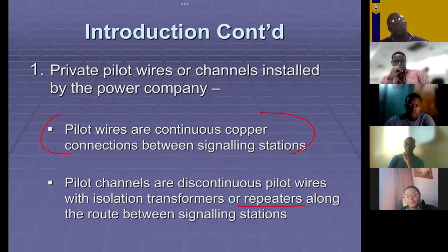Now, if you were to transmit or pass that information over the single copper wire, because you're dealing with ones and zeros, and the one is a threshold of 5 volts, okay? By the time it gets to where it's at, it may have fallen below that 5 volts or fallen even to below 3 volts and would no longer be recognized as a 1. Am I making myself clear? So what you do is to bring it up to a point where it does not fall below 3. And so you can reproduce it as a 1.